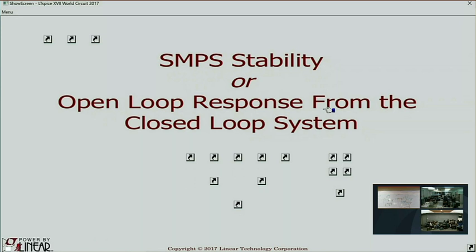First, look at the open loop transfer function and look at how the phase changes as you increase the frequency. You want to roll off the gain so that the gain drops to below 0 dB before you acquire 180 degrees phase shift.